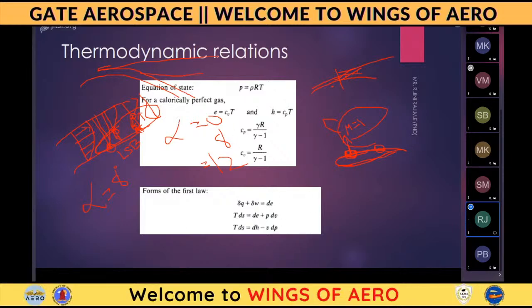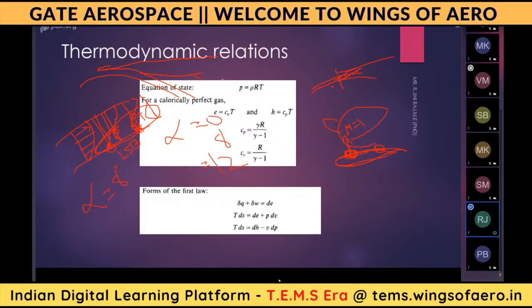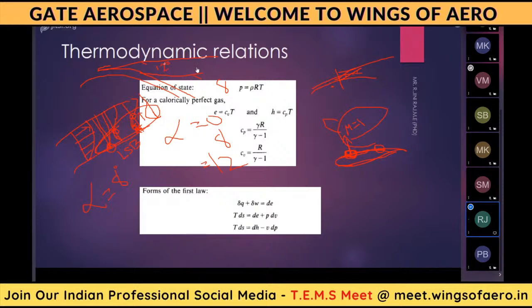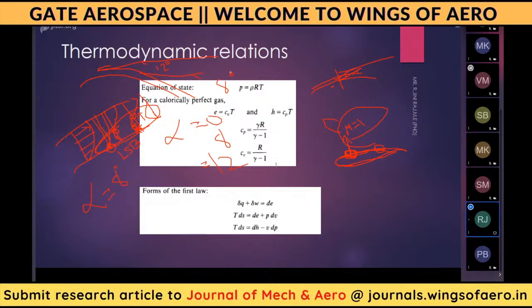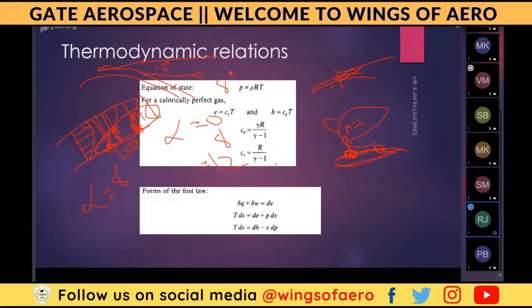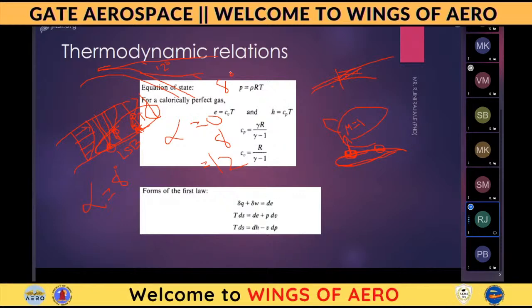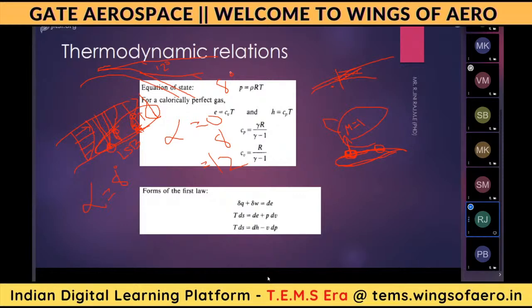See here, I have shown two diagrams. This one is for an angle of attack of 8 degrees, and the other is for an angle of attack of 12 degrees. If the separation moves forward, what will happen? The stall is increased. The main focus of the researchers is to design an aerofoil where, while increasing the angle of attack, the stall region, that means the separation region, should move further downstream only. It should not move forward.